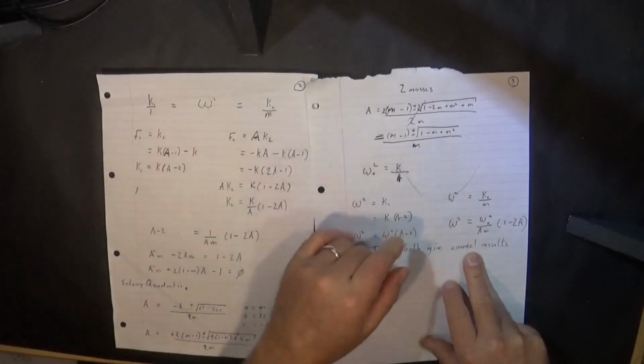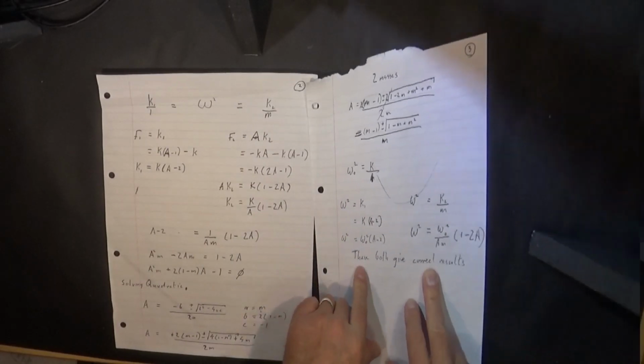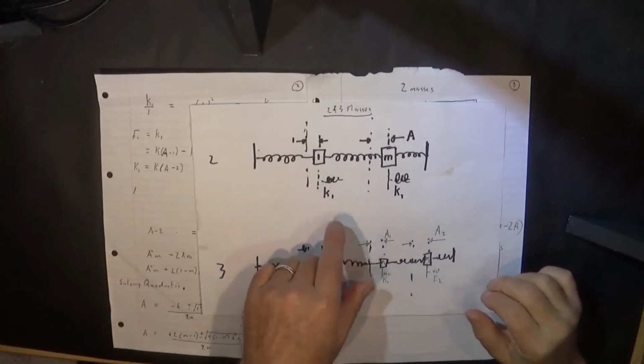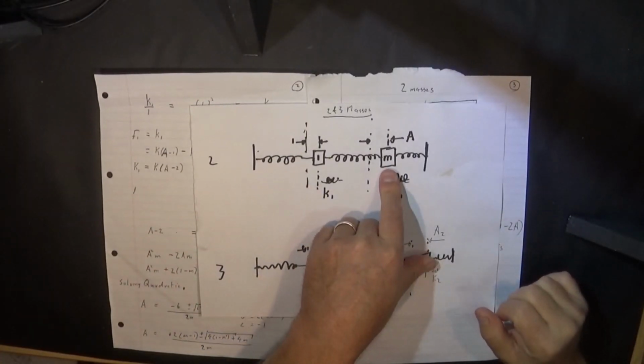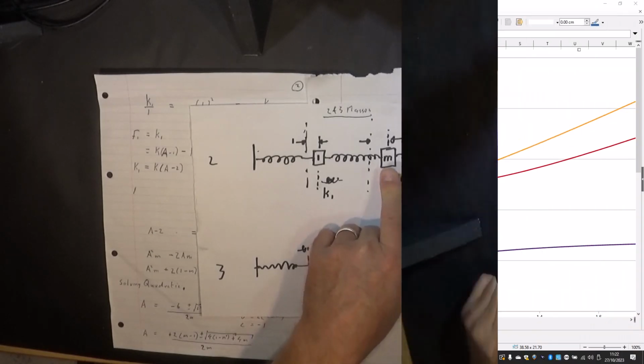I just swept frequency through the two mass system for various masses, so I'm happy with that. So now we can quickly find the resonant frequencies given our mass, so we can just calculate for various m's where they are and see what pans out of that.